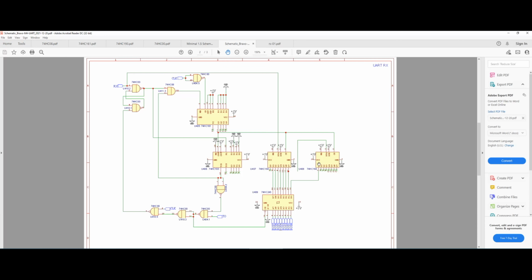However, the output of those chips is not going directly onto our bus. We just have a transceiver here, our beloved 74HC245 transceiver that we have been using in different modules in this computer. This chip takes the output of those chips and stores them as a buffer. And whenever we need to put that data back on the bus, we bring pin number 19 low, and that's going to do it. So this is the second part of the circuit, which is the serial in, parallel out part of the circuit.